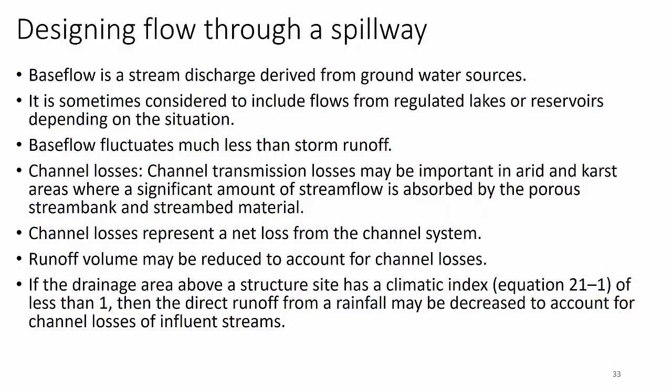Channel losses or transmission losses may be important in arid or karst areas like Arkansas, where a significant amount of streamflow is absorbed by the porous stream bank and stream bed material. I can tell you that is the case in most streams in Arkansas. We have as much as 50% channel losses in any given event. Channel losses represent a net loss from the channel system. You have to understand them in order to model downstream flows. Runoff volume may be reduced to account for channel losses.